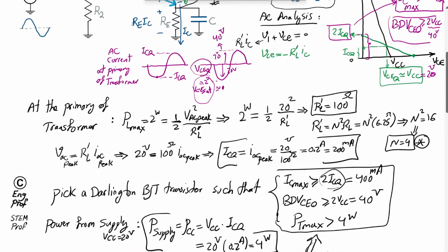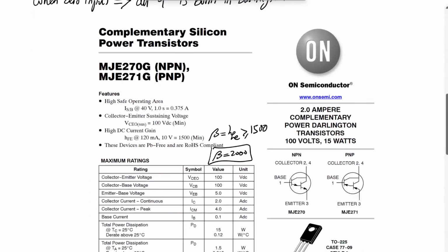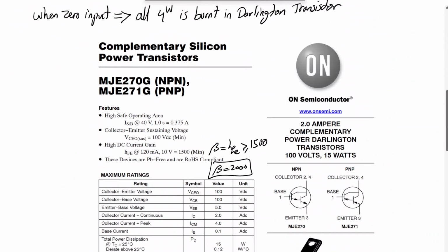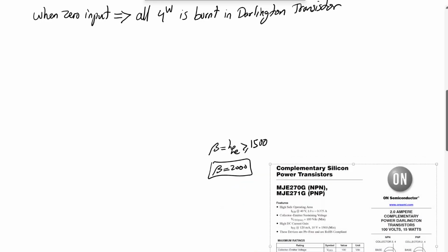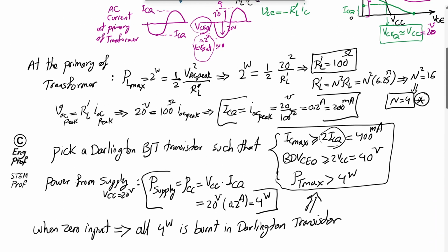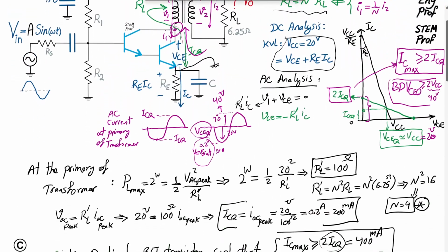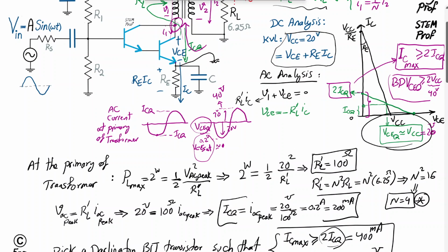So this is an example. Now, why does this matter? Well, the next step to find the DC component actually depends on the properties of the Darlington transistor we select. So in this case, if I go back, for this approximation, the only requirement is RE. So I'm going to put it here. It's a practical part of the design.